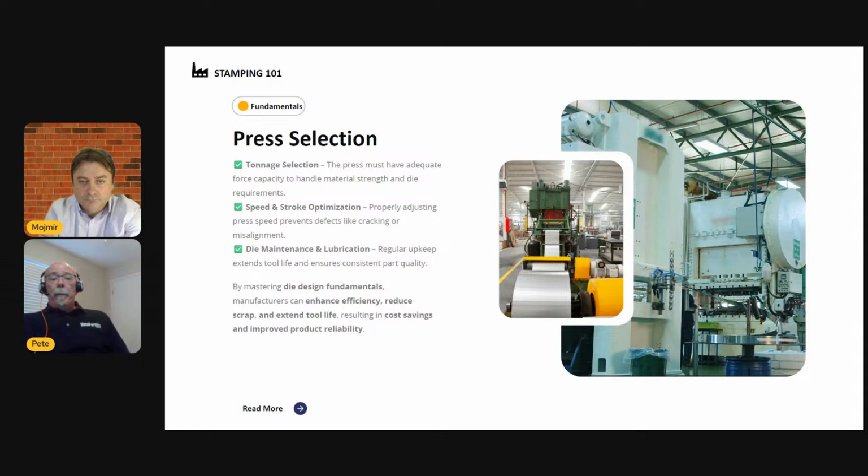So we have to take into account press energy, because I'm working so much longer, the flywheel in the press is beginning to slow down and I'm losing energy out of the flywheel. And now I don't have enough energy for the next stroke to make the next part.